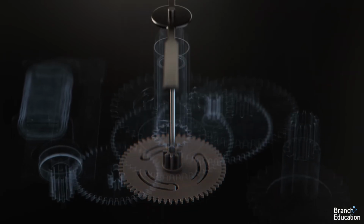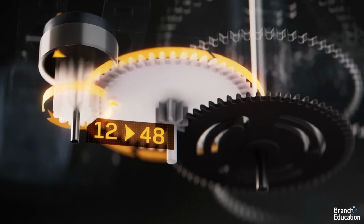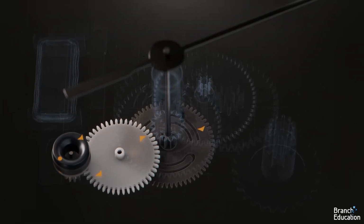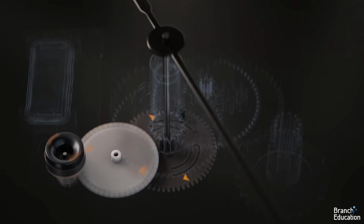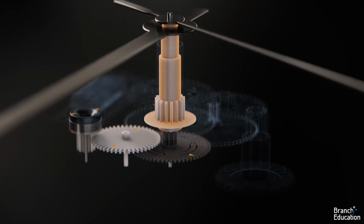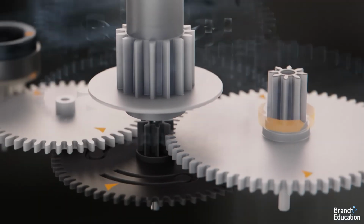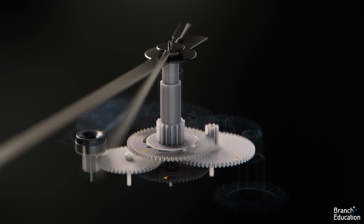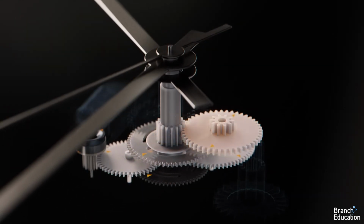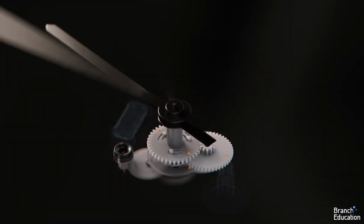To move the second hand, which is mounted on a shaft through the clock center, we go through a 12 to 48 gear reduction and then an 8 to 60 gear reduction, thereby reducing 1 revolution every 2 seconds down to 1 every 60 seconds. The minute hand is also mounted on a shaft through the center and is driven through an 8 to 64 gear reduction to the idler, followed by 8 to 60 to the minute hand. And finally, the hour hand is driven via a 15 to 45 reduction to the idler and a 10 to 40 gear reduction to produce 1 rotation every 12 hours.